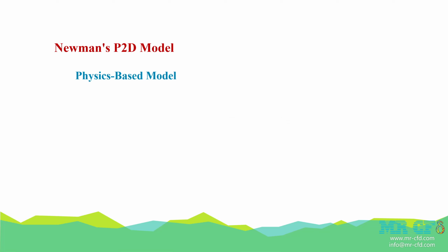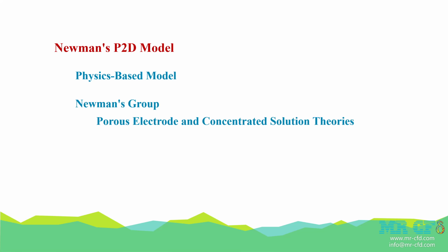Last, we refer to Newman's P2D electrochemical model. Unlike the semi-empirical NTGK and ECM models, the P2D model is physics-based. In other words, Newman's group has developed a physics-based model using porous electrode and concentrated solution theories. The P2D model accurately captures the lithium ion's migration inside the battery.